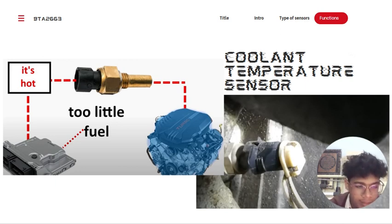Like almost all the other temperature sensors, the coolant temperature sensor must come into direct contact with the fluid whose temperature it is trying to measure. As such, you are very often going to find a coolant temperature sensor near the thermostat. Some cars have more than one, and you can find them anywhere on the coolant piping or wherever else coolant is passing through.